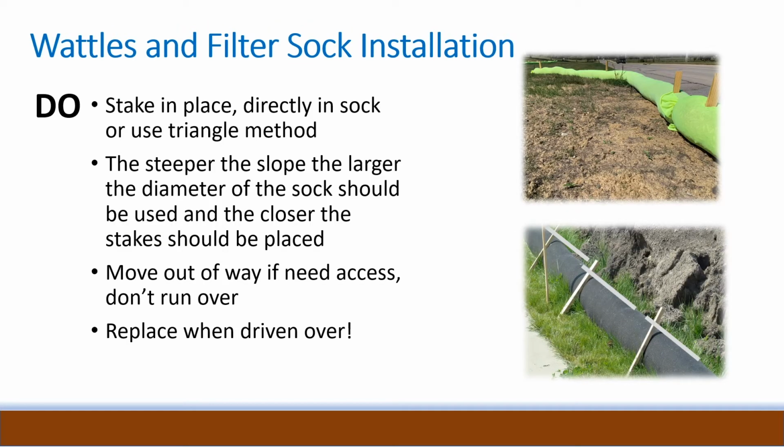Waddles and filter socks are placed on the soil surface. Stake them in place directly into the sock or use the triangle method as shown. The steeper the slope, the larger the sock, and the closer the stake should be placed. Move these practices out of the way if access is needed. Don't allow them to be run over. Replace if they happen to be driven over or if they are torn.